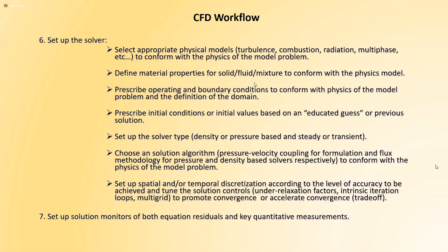Define material properties. As a suggestion, read the guidance of the specific platform. For example, in Fluent, in a mixture of water and air, you need to put the water before the air if you want to get humidity. It's simple stuff that can get you stuck. But of course, the definition of material properties is very important.